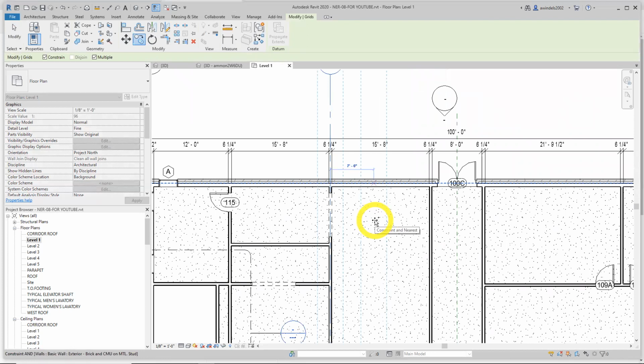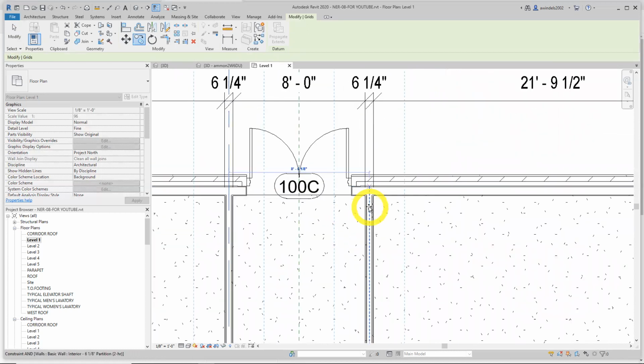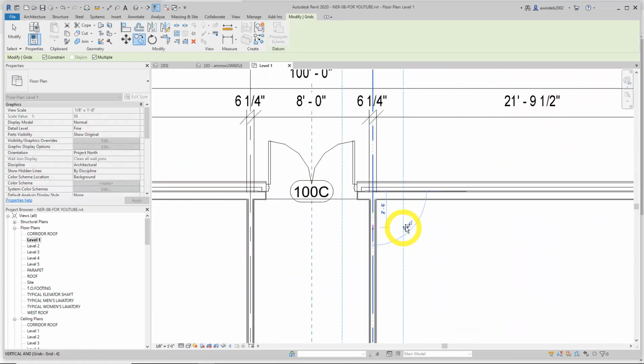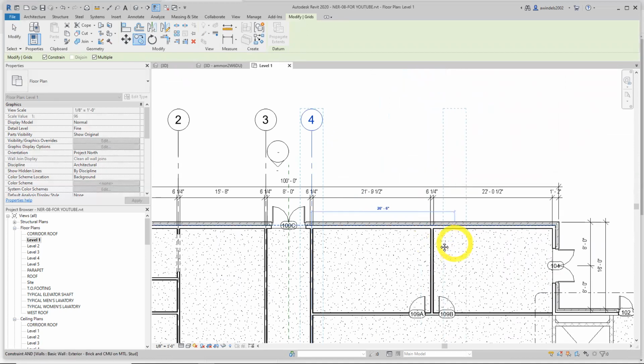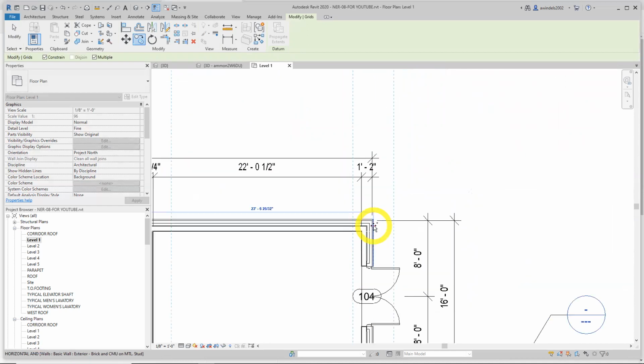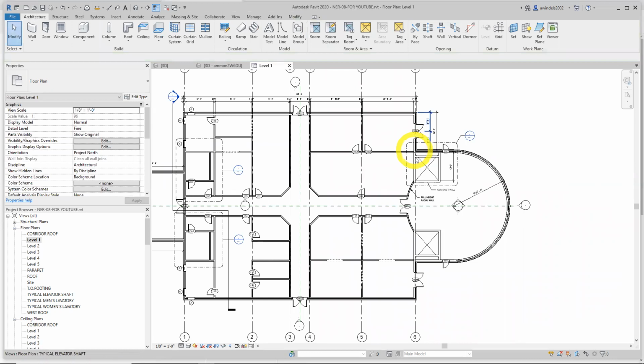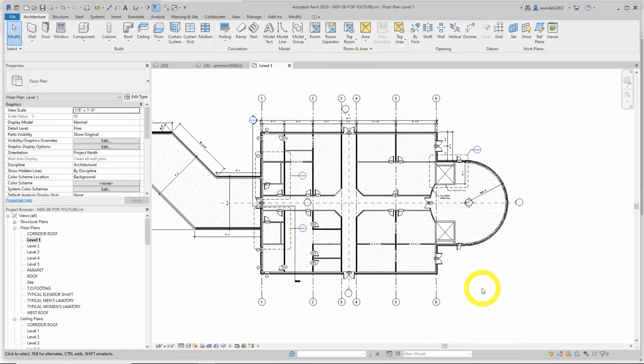And let's continue on to the picture on figure 8.7, doing grid line 3, grid line 4 to the center. Grid line 5 to the center of this interior partition wall, and grid line 6, this center, not to the center of core of this exterior wall. Okay. Just making sure I got grid line 6, that looks good. And we'll have our 6 first grid lines, and they match each other because I copied what I wanted and I got that started on the right foot.